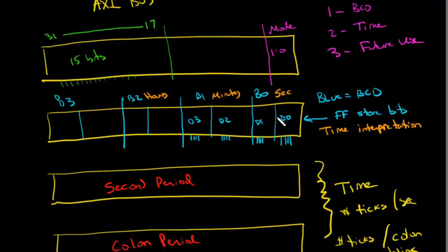Now the time module has one further complication, and that is we like to store time as either 12 bits or 24 bits. And that's also kind of one of those status registers. And so we'll make register bit 2 here be 12 or 24. Now, this is all going to be what drives all of the rest of these control units.